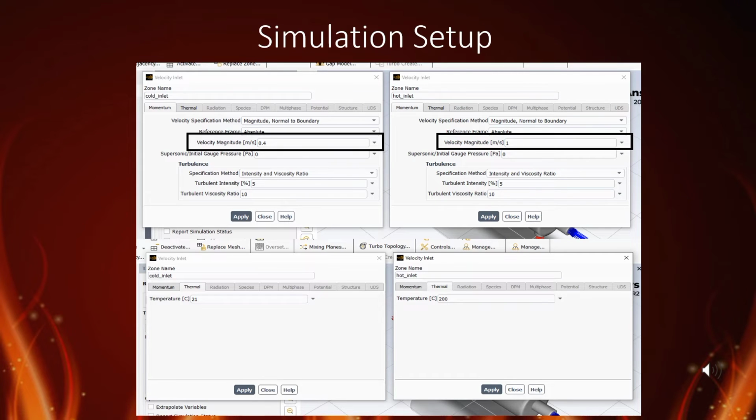The capacity rate being calculated as the flow rate multiplied by the specific heat. In the result, the temperature ranges for the animations had to be set to different values for the tube side and shell side animations so that the change in temperature for each fluid could be more distinct.